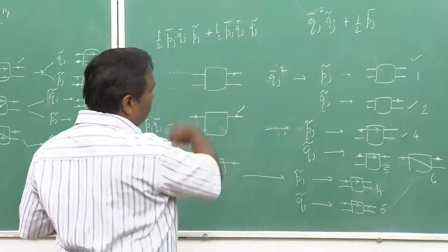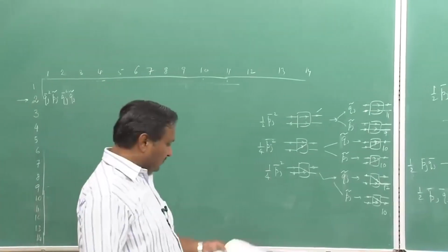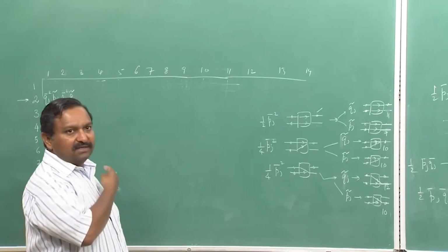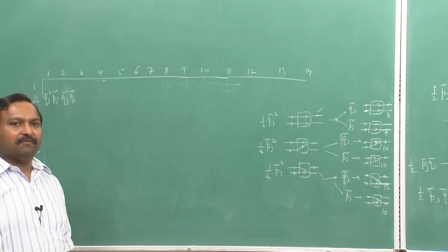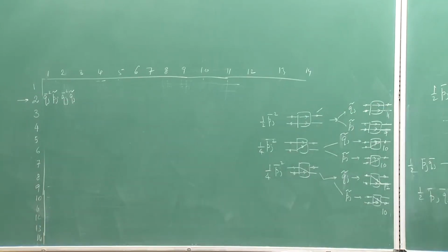Okay, so you have to keep on solving in this fashion and ultimately put up the values of the matrix, and once you have this you have to again do the same iteration until you get a steady state flow, and based on that you can find out the throughput performance. So, this is actually complicated, so I am leaving it to you to do it on your own. Once you understand the concept you can always start analyzing the buffered system.